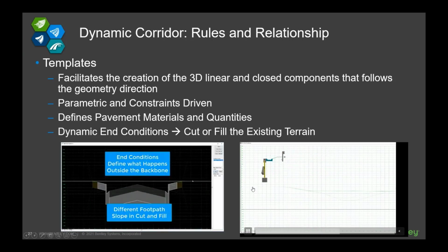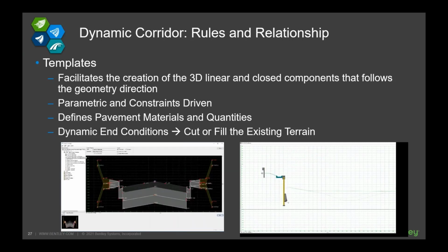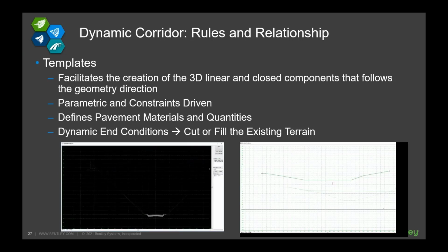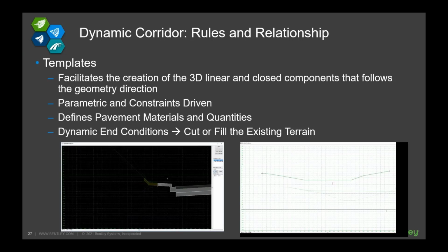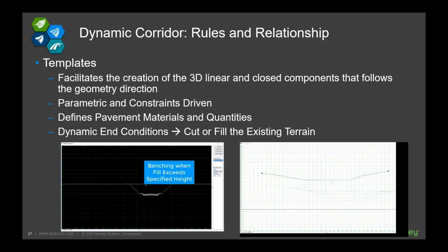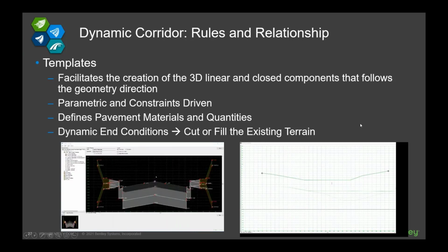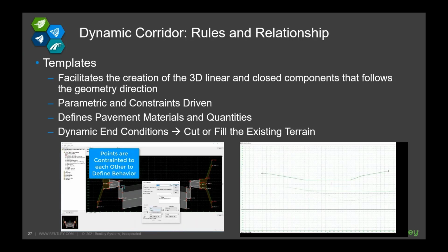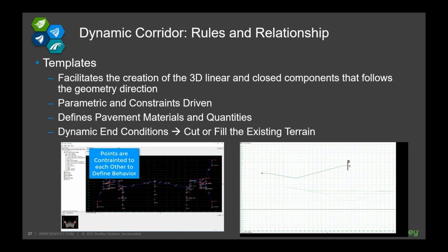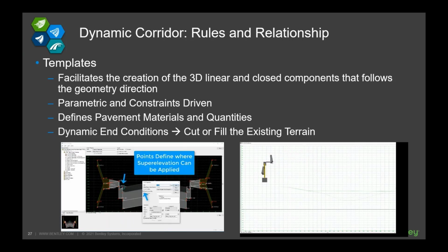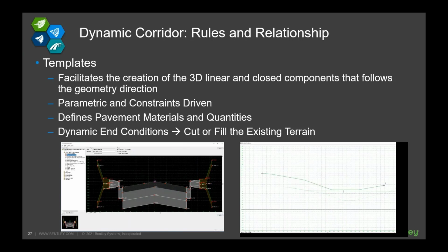So I guess we take one more question. This person, I think, is a Civil 3D user. He's asking, how do we migrate the data over into OpenRoads? Very good. I like that question. For those who are migrating or probably still using Civil 3D, we have tools that will allow you to import. Maybe you start with terrain, so you export your terrain from Civil 3D to LandXML. Then your alignment as well, export it to LandXML. And then inside ORD, we have a way for you to import that LandXML so that your terrain as well as your alignment can be converted into DGN.